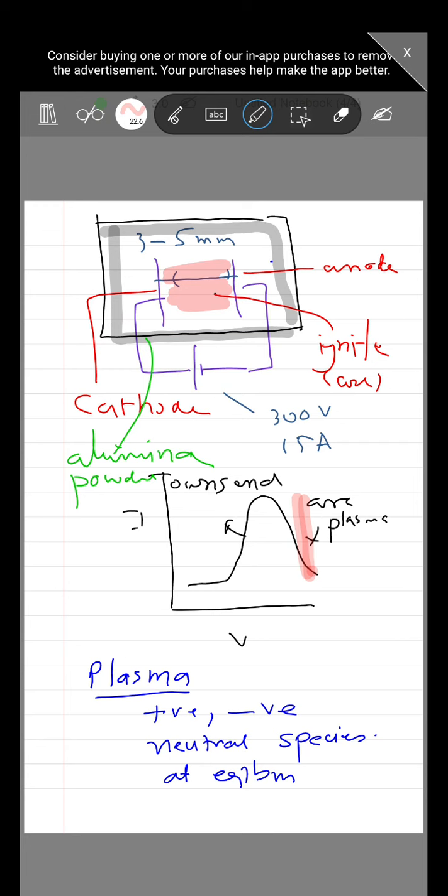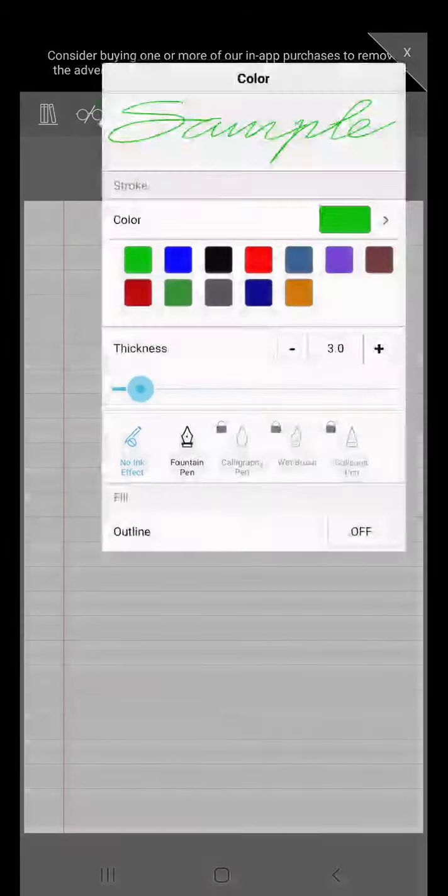Now, after this deposition has taken place, we offer cooling of the interior, and the powders are gently scraped from the roof of the chamber and collected for analysis. Mainly, it's on the roofs. So this is the second way by which we can produce nanoparticles, especially alumina. And now the third technique is called sonohydrolysis of alkoxide precursor.